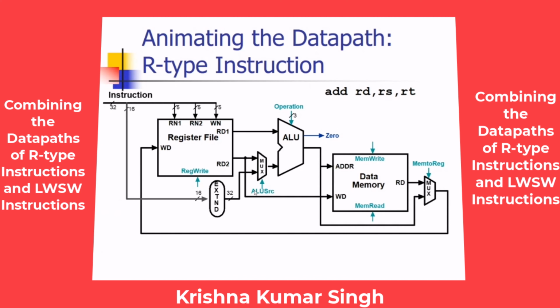First, for the R-type instructions. Let's see which part of the data path will be used. So the RS and RT come from the instruction and are given to the register file, then two data values will be read from the register file. One of them is directly given to the ALU. Another one will be given to this multiplexer. ALUSource will select which one of these two inputs should be given to the ALU. In this case we are going to use the upper input, so the ALUSource should be 0.